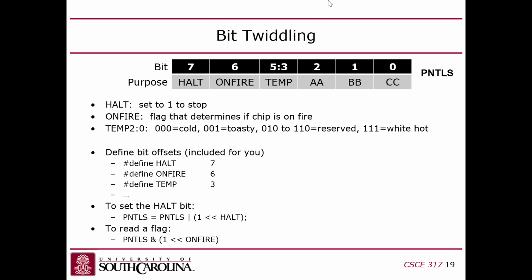So that way, what you're ANDing it with would, instead of like here, where you're ORing it with 1 0 0 0 0 0, or actually, I'm missing 2 because that's 3 bits, but 1 and 7 zeros, that's what you get with this shift. But if you ANDed it and you wanted to make it a 0, you'd want it to be 0 and then 7 1s here, which means that you can take this and you can complement it and use an AND.